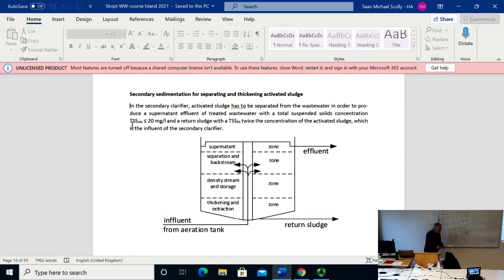We have again the criteria. Our water has still the same viscosity and the density of 1. The activated sludge, which we want to separate here, has a density, however, very close to the water, maybe 1,050 to 1,100. We do not know any diameter, and we do not know any form of the sludge flocs.